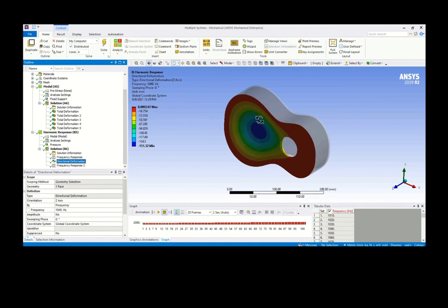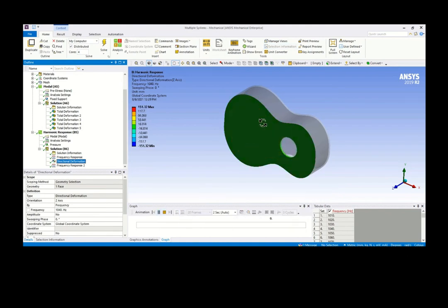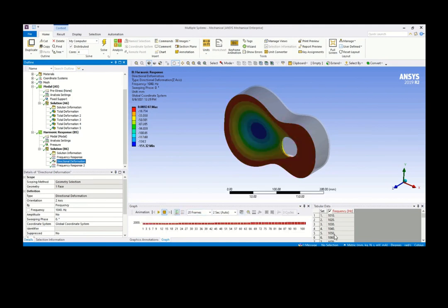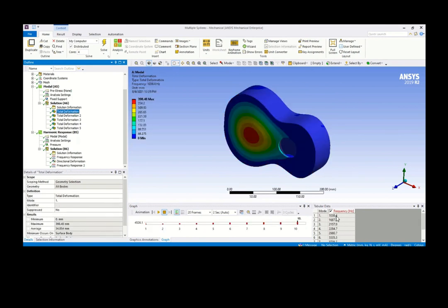This one you can actually see how it moves. Why does it deform like this? Because it's very close to the first natural frequency. The main contributor of this particular response is the first mode. So what if I go in between the first and second, 1040 and 1690? If I put 1500, what will be my response?